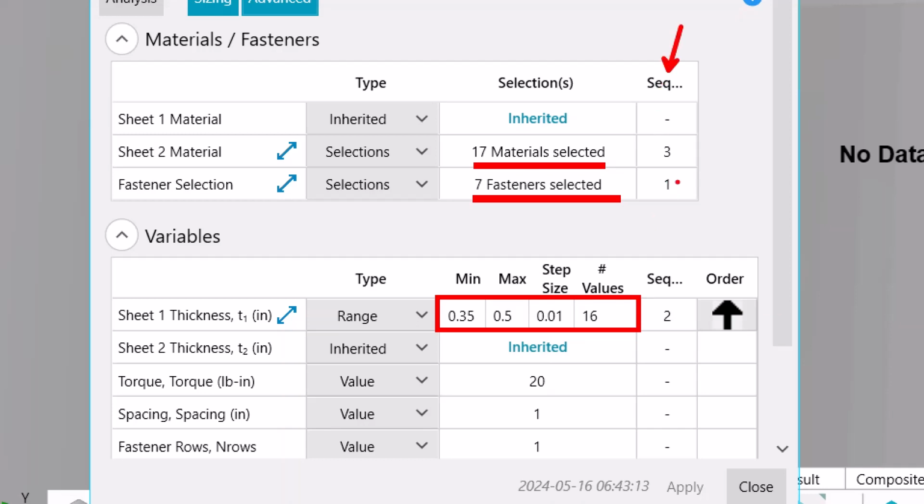So the order of operations that I've specified here, number one is try a new fastener, upsize the fastener. Then increase the plate thickness to try to fix the negative bearing margins on the plates. Then increase the laminate thickness to try to resolve the negative bearing bypass margins. If you don't get positive margins, start over, go back to number one, select a new fastener.